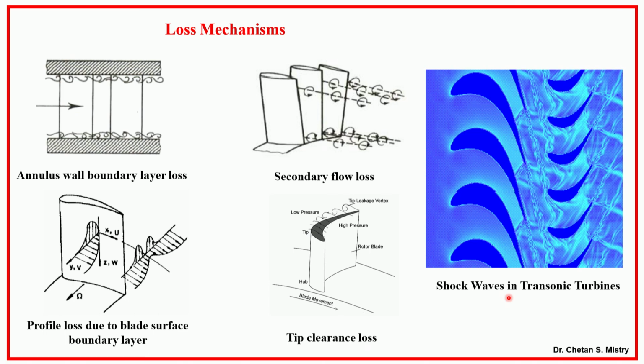Now, here if you look at it in an overall sense, this is a picture. A very interesting case happens when we talk in terms of your HP turbine or HP nozzle. Here this represents my shock structure. This is the wake coming out from my trailing edge. Somewhere here I will have my shock present. Here in this particular region we will have an adverse pressure gradient. So we will have the formation of separated flow.